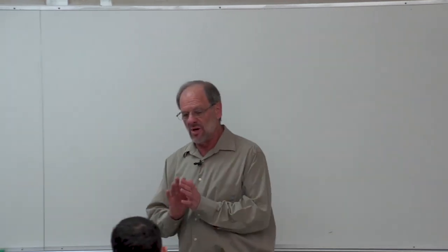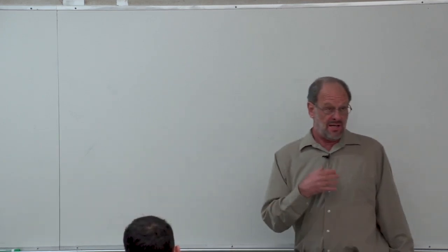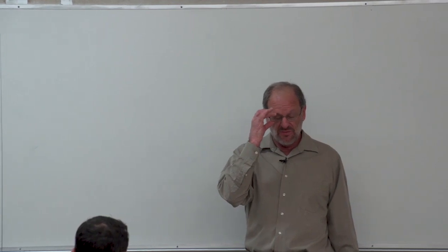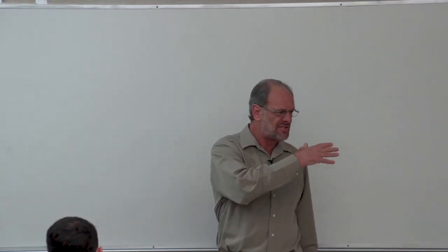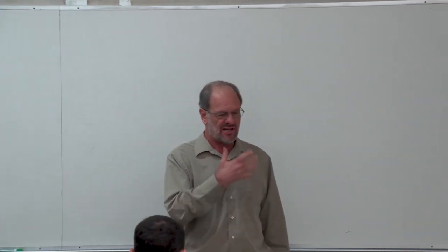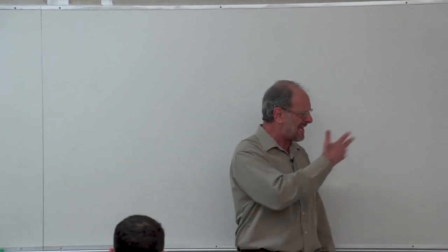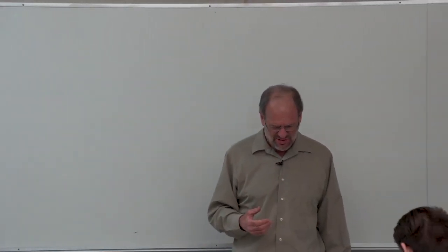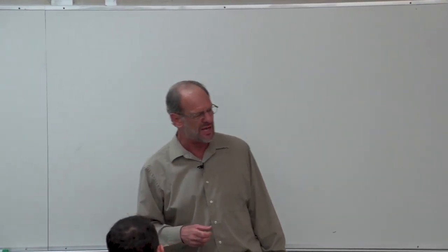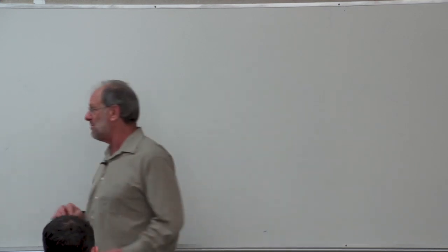All right, then one other thing to note at the beginning. Last time, as I was discussing the example problems for the Otto cycle, clearly I was having a couple of issues here and there. And I finally realized it all stemmed from one thing: the compression ratio is V1 over V2, not V2 over V1. In my mind, I kept looking at the board and copying pretty accurately from my notes, but I just wasn't getting the right looking equations, and then I finally figured it out. But I hadn't figured it out earlier as I was going through the first example.